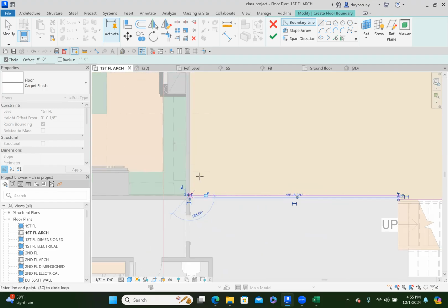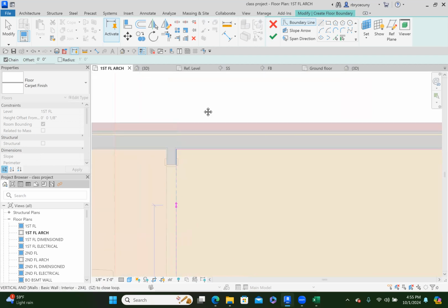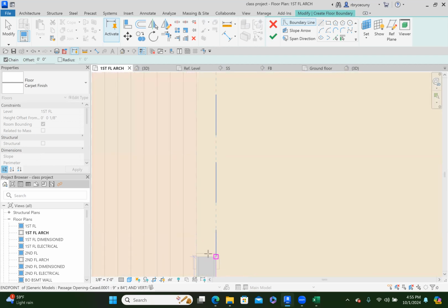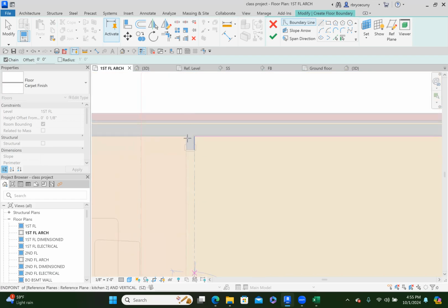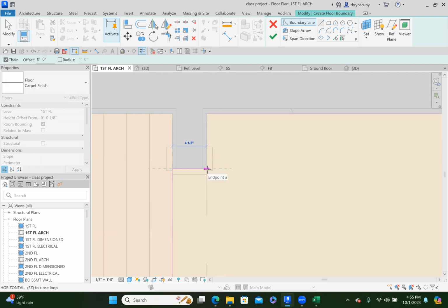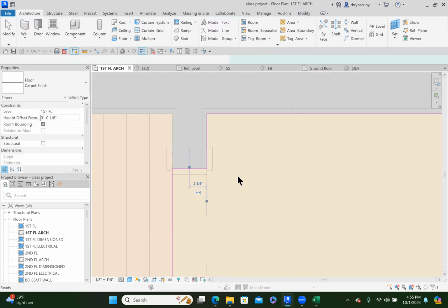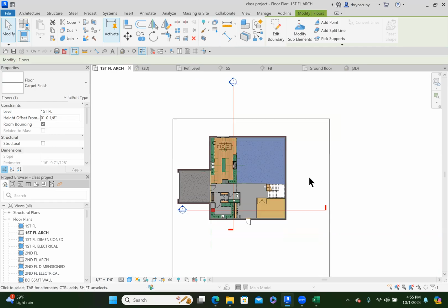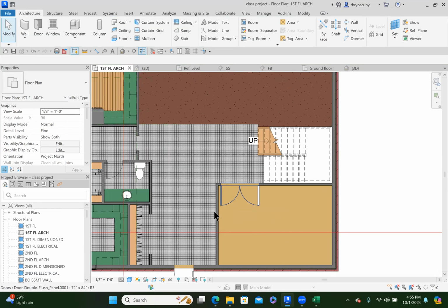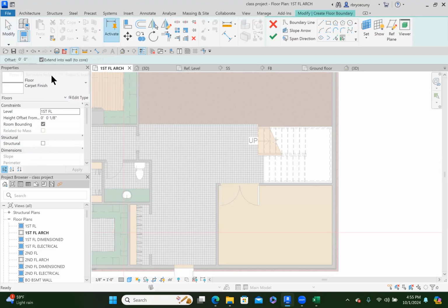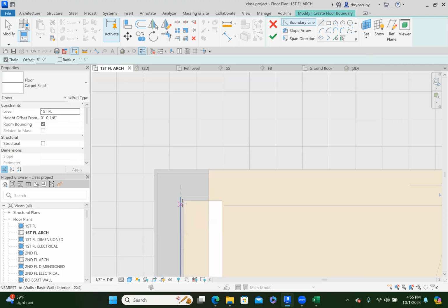Of course, you're the architect for your project, and you can put whatever material on the floors as a finished material that you want. Say okay. Look at that carpeting there. And we'll put carpeting in the office or library as well. That I think I can do with, I'm going to go up to here with it. I was going to say I could do that with a rectangle. Now it defaults back to the last material that we selected, so it's still carpeting. It's going to do a rectangle, but I'm going to take the carpeting right up to the tile over here.